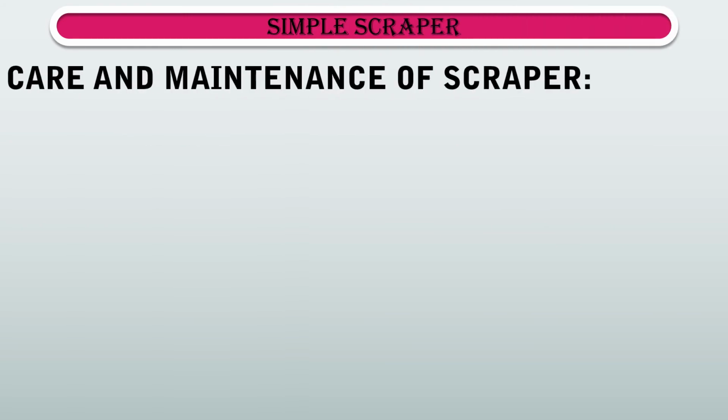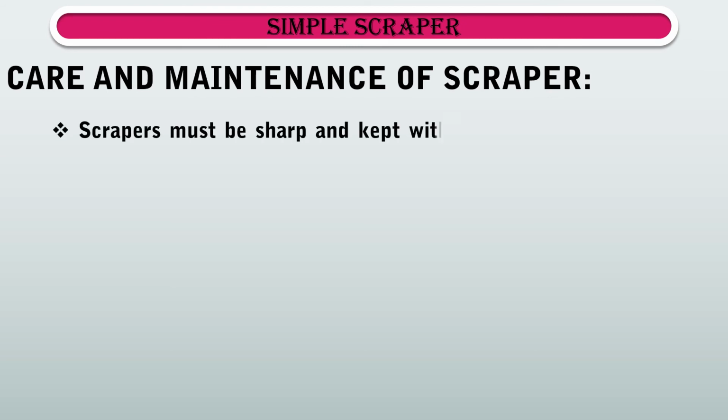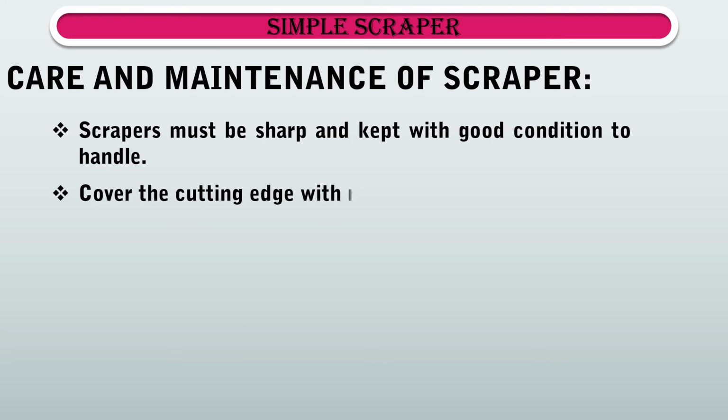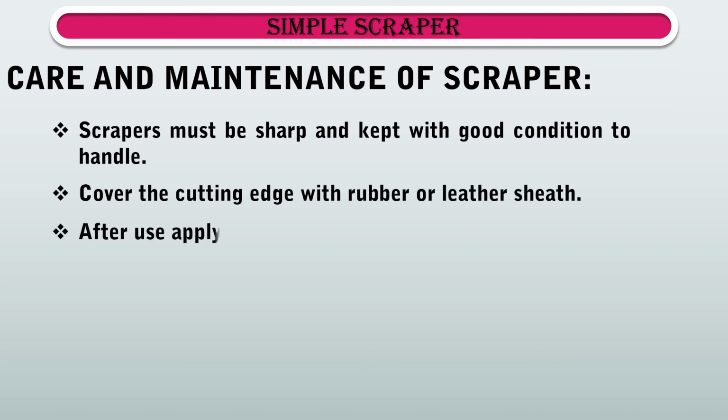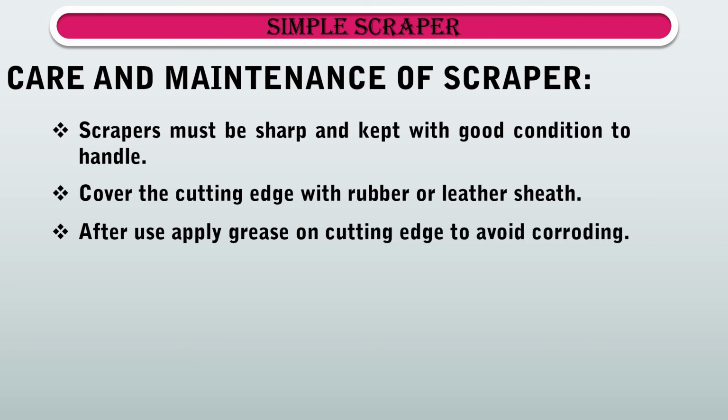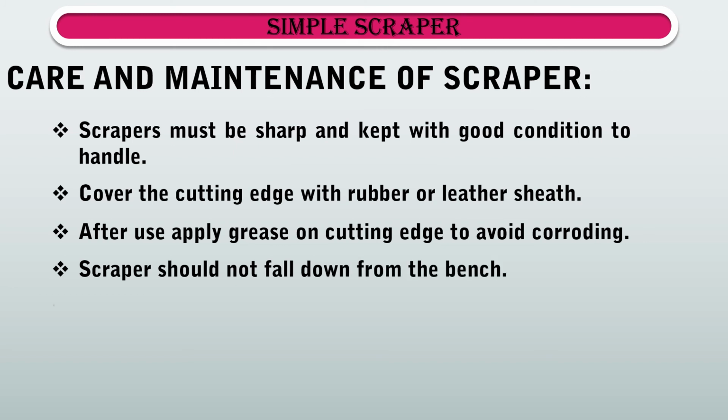And last, we are going to see care and maintenance of scrapers. 1. Scrapers must be sharp and kept in good condition to handle. Cover the cutting edge with rubber or leather sheath. After use, apply grease on cutting edge to avoid corroding. Scraper should not fall down from the bench. Don't mix with other tools.